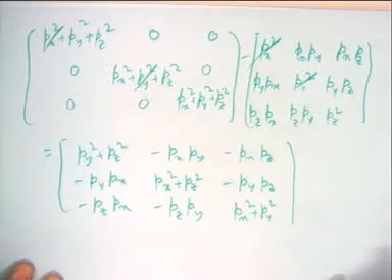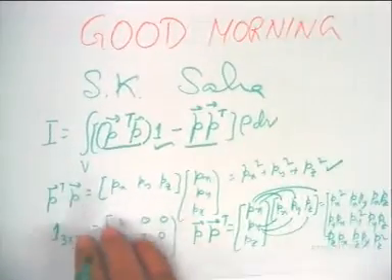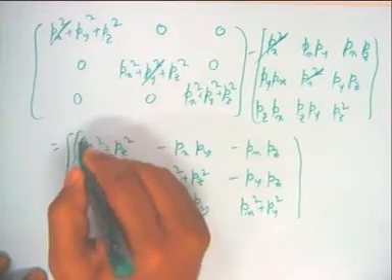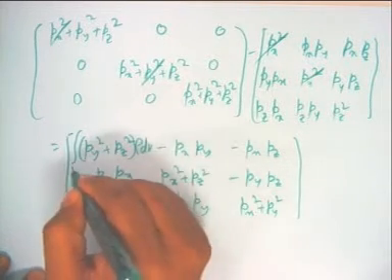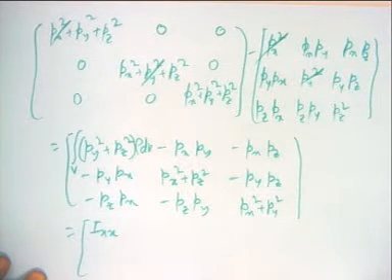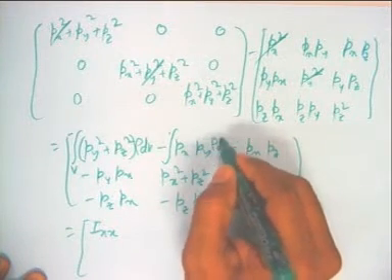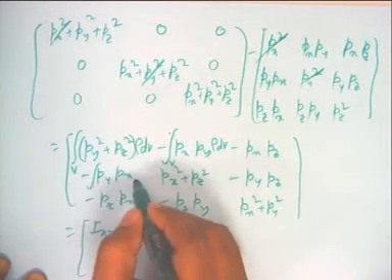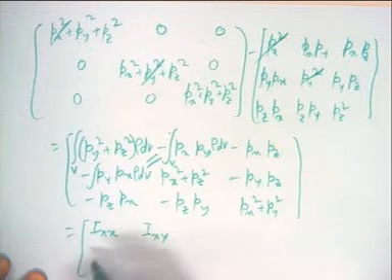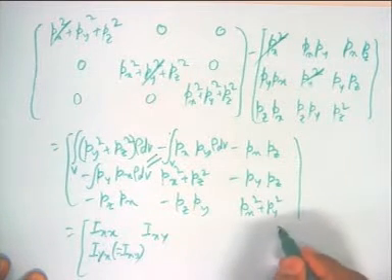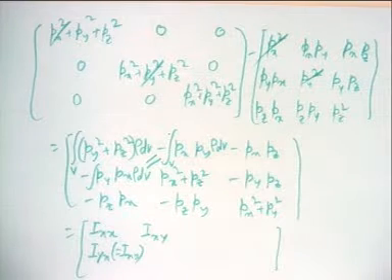Now, if you look at the expression in the previous page, just let me show you for a while. This rho dV integral over V will give you the element. So, let us integrate. Integration of rho dV over V will give you the first element of this inertia matrix, which is called Ixx. You integrate this rho dV over V, this will give you Ixy. I integrate here rho dV. Now, you will see these two are same. So, even though I write Iyx, that is equal to Ixy. So, this is the way the I matrix can be calculated mathematically, okay.